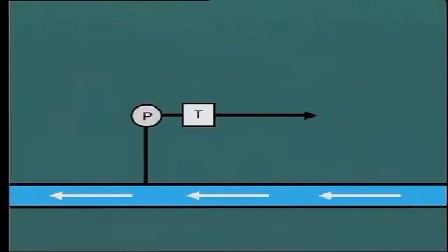In modern installations, a transmitter produces digital signals for transfer to the computer or central processing unit in the control room. The digital signals have the advantage of being faster and being able to transmit a higher volume of information. Another advantage of the digital control system is its ability to continuously check incoming readings for accuracy and abnormal indications. It does this by comparing multiple readings, computing averages and implied values, so that any obviously incorrect signal is discarded before it can bring about faulty positioning of the auto controls.